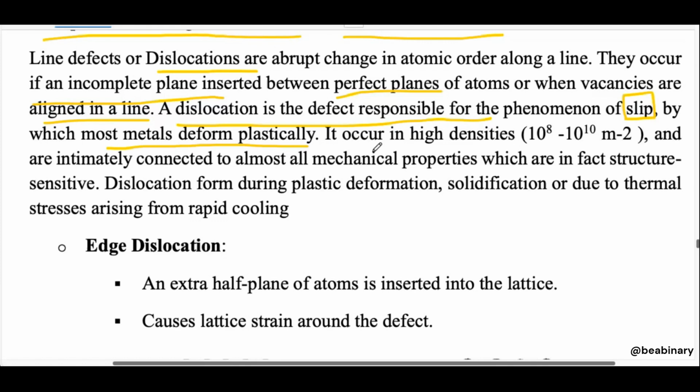Because the resistive force by the body is more or less equal to the applied force, up to the elastic limit where it can regain its shape. That's why we can directly correlate this. But the correct way to say it is that the load is the external thing that we apply, and the stress is what the material induces in itself due to the applied load.